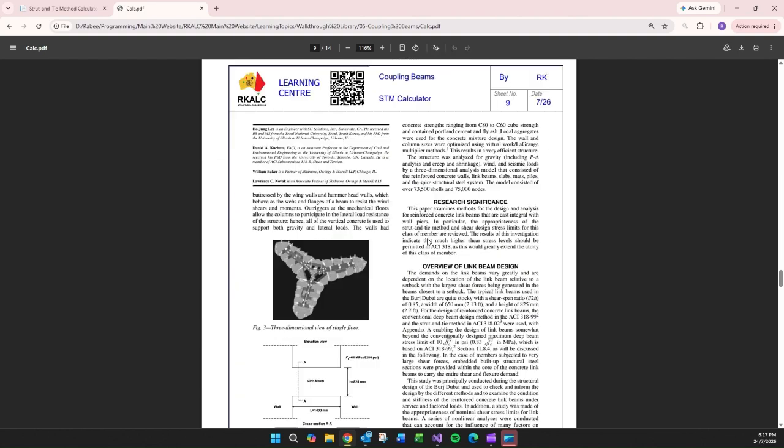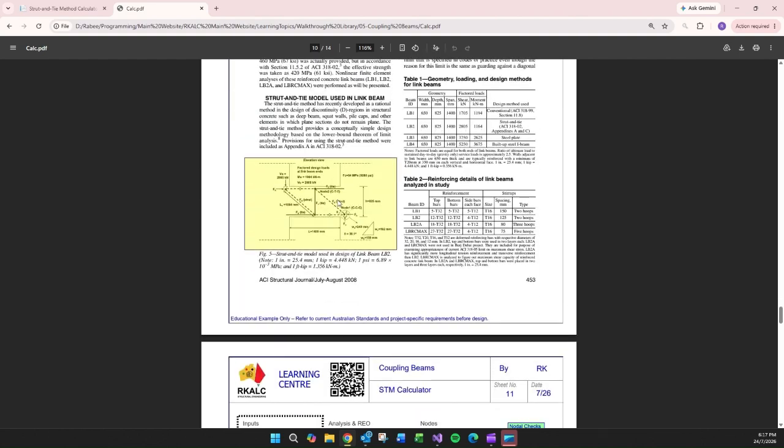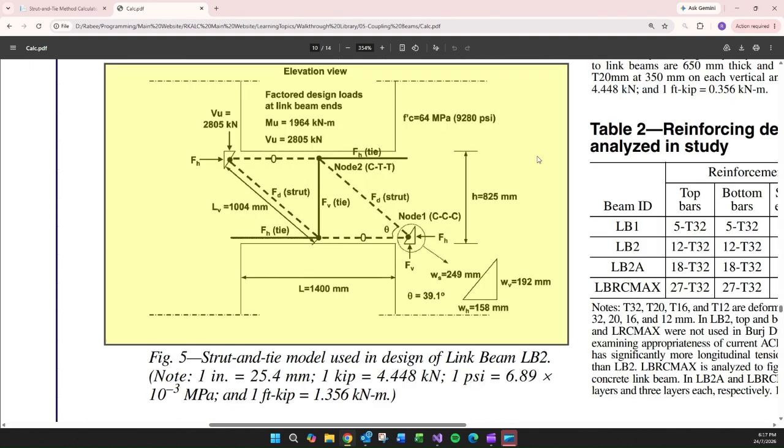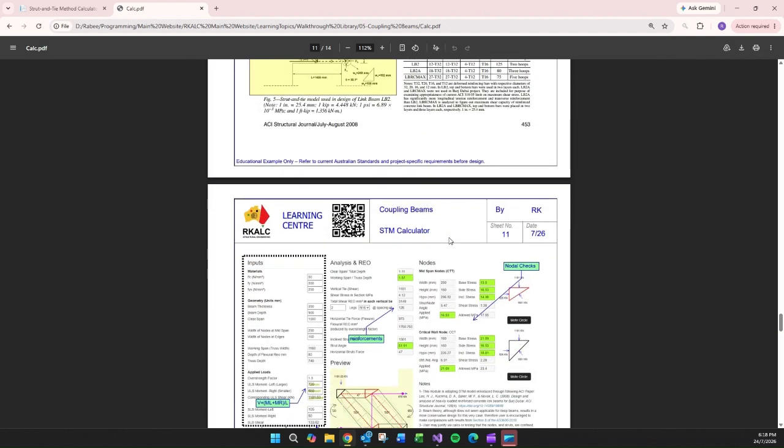So they came up with this model, the Strut-and-Tie model for beams that many people recognize, where the ties are the dark ones there. That is representing the flexure, and this one represents the shear, the tension in a beam in a vertical direction. Everything else is struts, and you've got nodes, the wall nodes, if you want to call them, or middle nodes. So that is the approach that we are having.